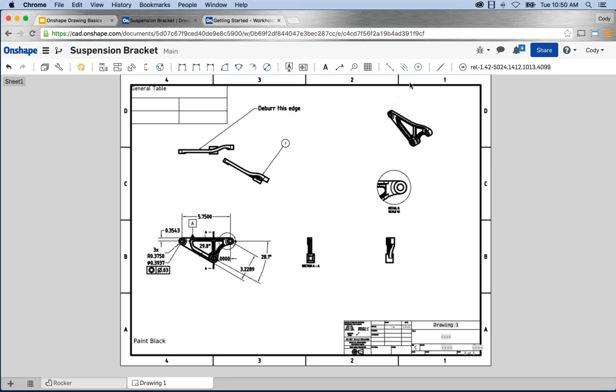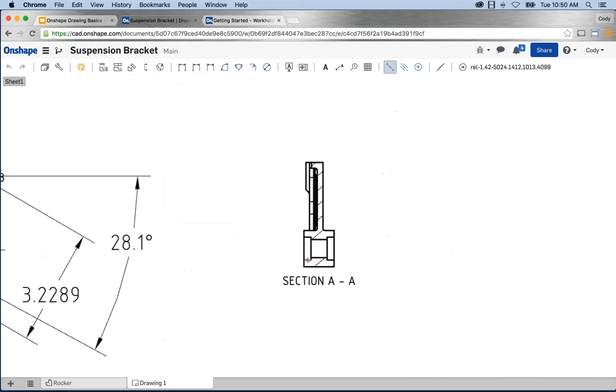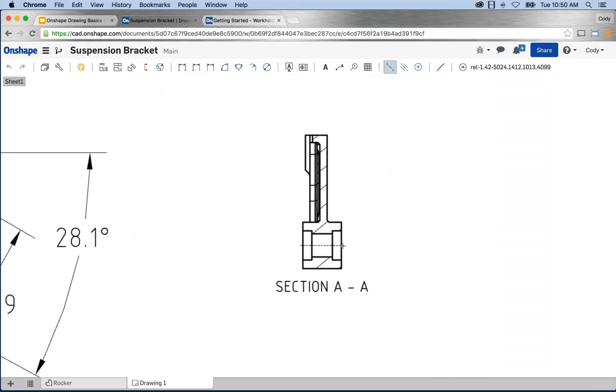Then we get into some of the other annotation types, things like construction lines. We have two different types of construction lines, and then circles. And these are primarily to construct geometry for references. So I can select 2-point center line, for example, and select a point, and it creates a center line. Right. I can even drag the endpoints of these lines and extend them, so I can manipulate them. So you do have some control. Again, very similar to a 2-point dimension. Left click, and then manipulate as you choose.